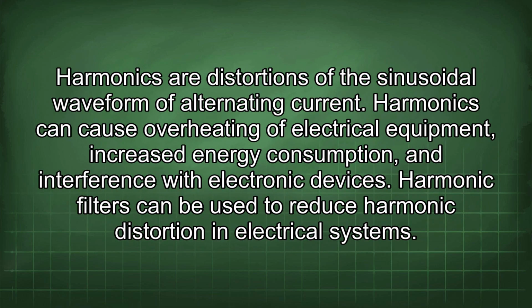Harmonics are distortions of the sinusoidal waveform of alternating current. Harmonics can cause overheating of electrical equipment, increased energy consumption, and interference with electronic devices. Harmonic filters can be used to reduce harmonic distortion in electrical systems.